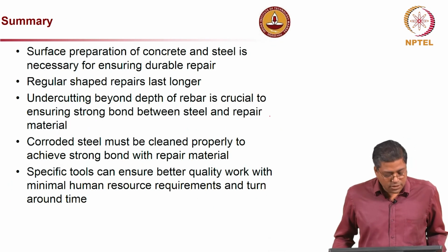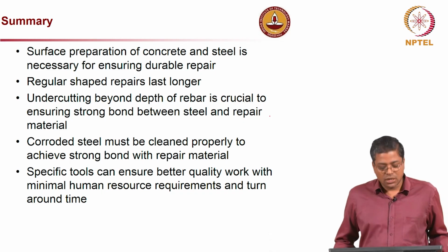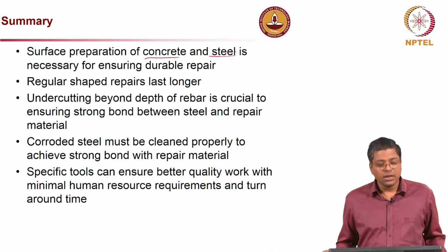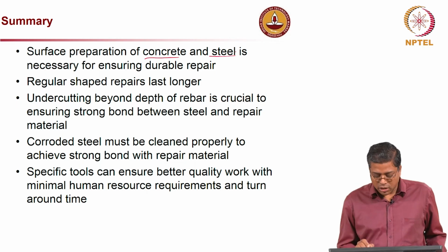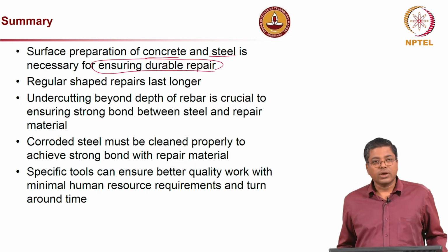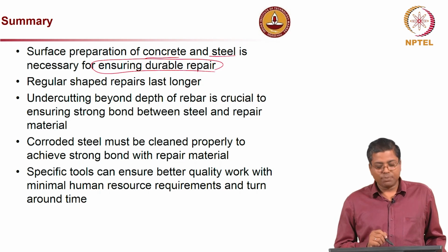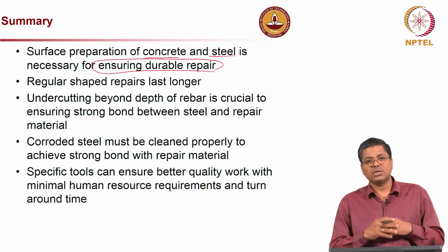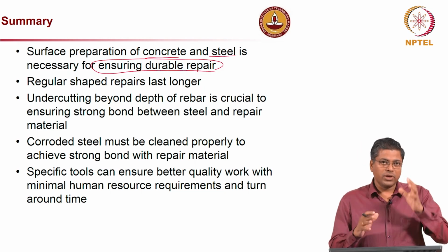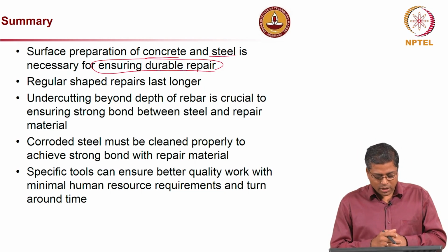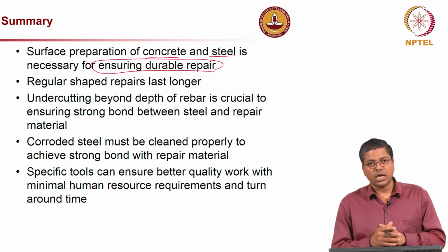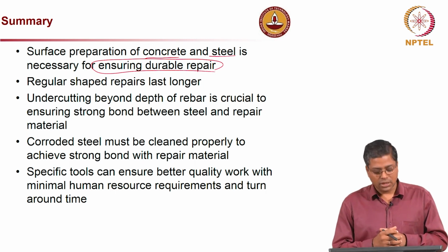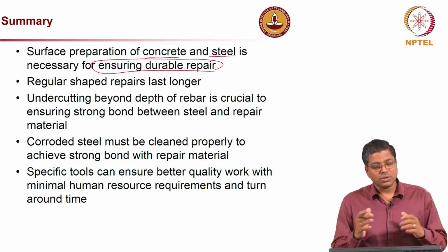So to summarize, we talked about surface preparation of both concrete and steel. It is very important to ensure durable repair, and regular shape repairs last longer, because in an irregular shape there will be stress concentrations, and the quality of the work will not be as good as compared to a simple shape. That also helps in estimating the amount of materials required, and it is also aesthetically pleasing.